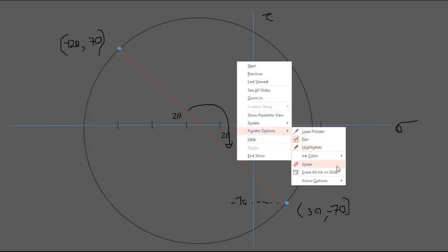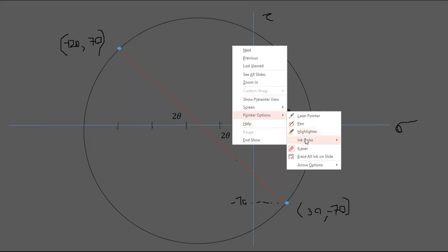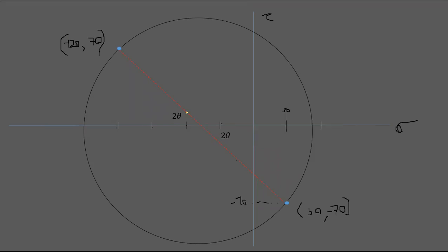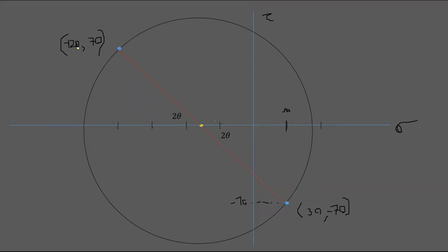In the Mohr circle, any angle in the element will be doubled in the Mohr circle, right? So if it is 180, this is the diameter of this circle, right? So you can find the center, right? You just need to add these two together and divide it by 2.